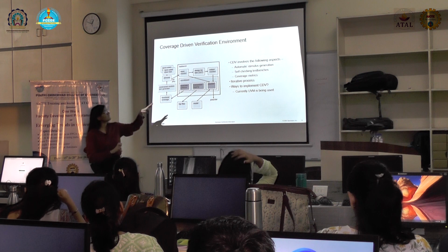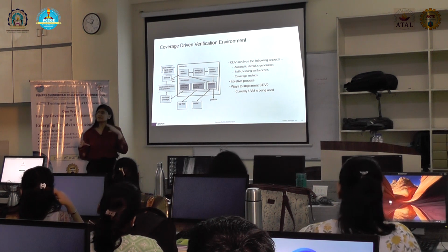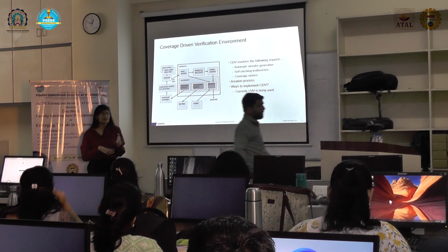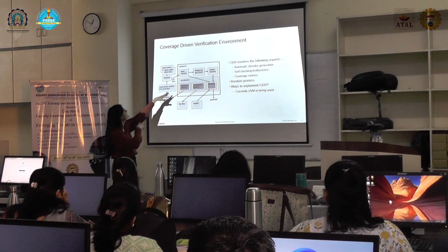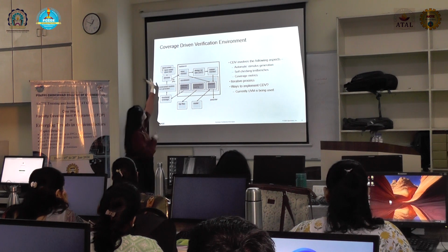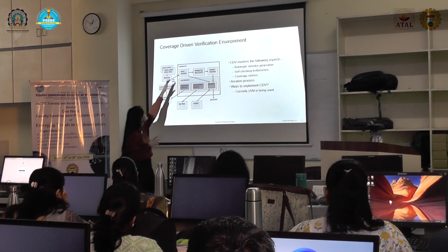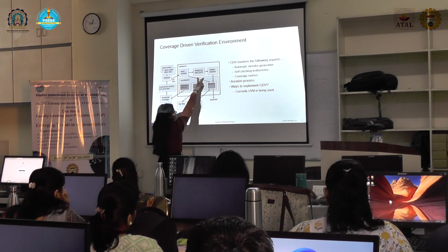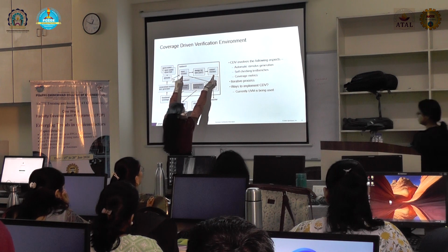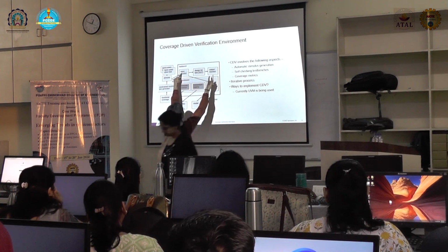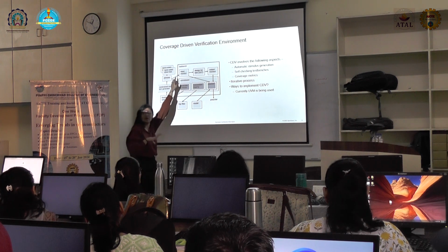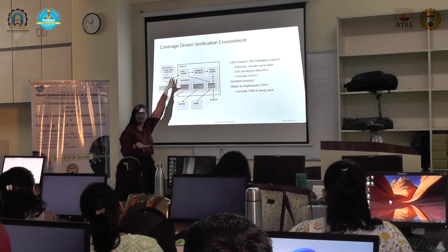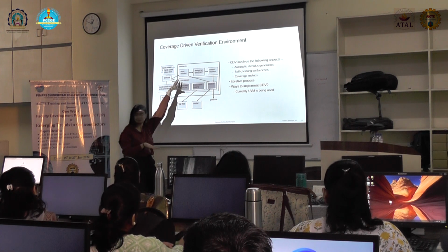So in that case, we require a different structure from what we traditionally followed for the Verilog structure. In this particular structure, we have components such as the DUT, which is the common one. We have monitors, and the input monitors are there. These are the drivers. It's all class based, so it's all a template, and we manipulate that template using objects.